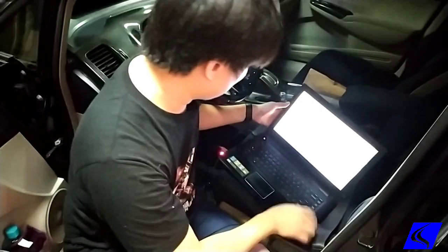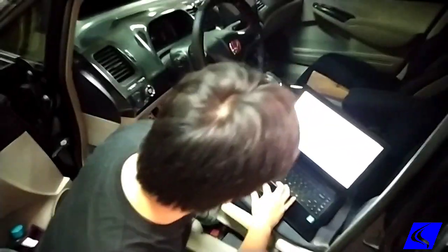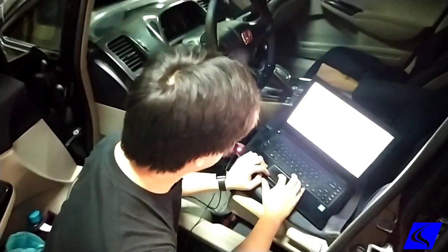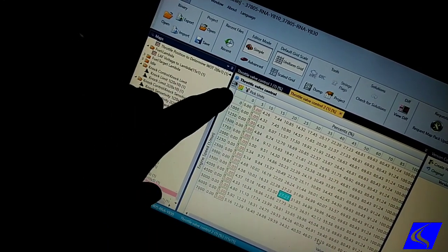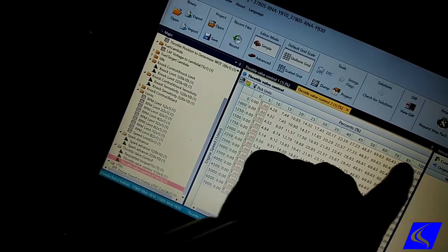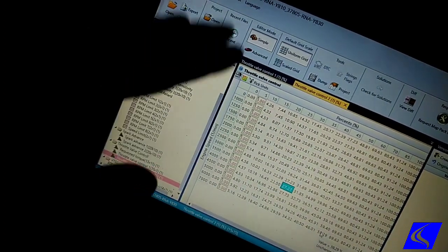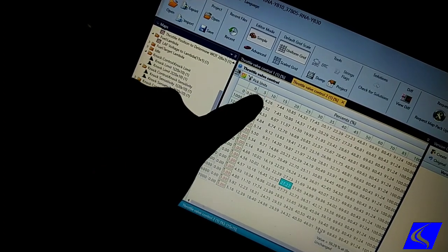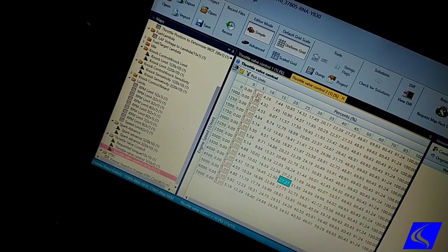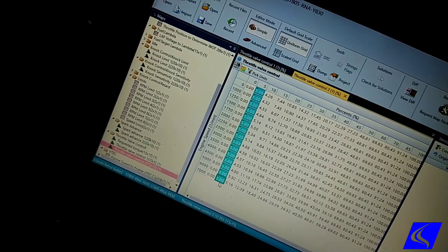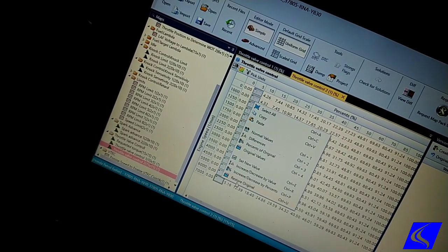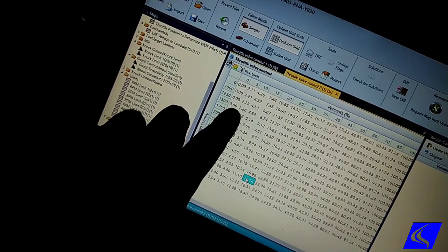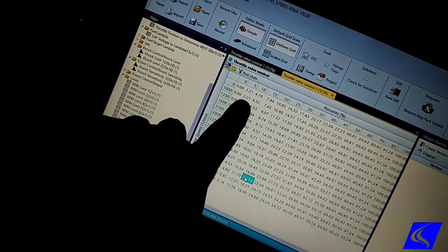So first things first we do what everybody likes, is this one. We adjust the throttle valve here. So basically this is RPM, this is pedal applied, so how much you tapak. Then this is how much the throttle opens. As you can see here, this value before was, let's put it back to original, 2.21. So for 5% tapak, throttle only opens 2%.